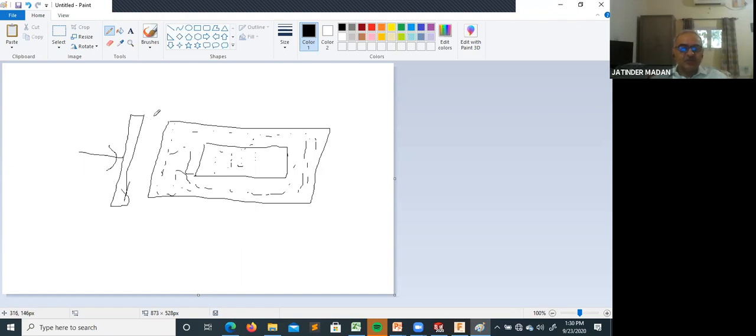Now, this roller will go back after sprinkling the powder. You have a very thin layer of, say, 0.5 mm. Now you have a laser gun which is going to throw light in this area only. Laser beam for sintering.